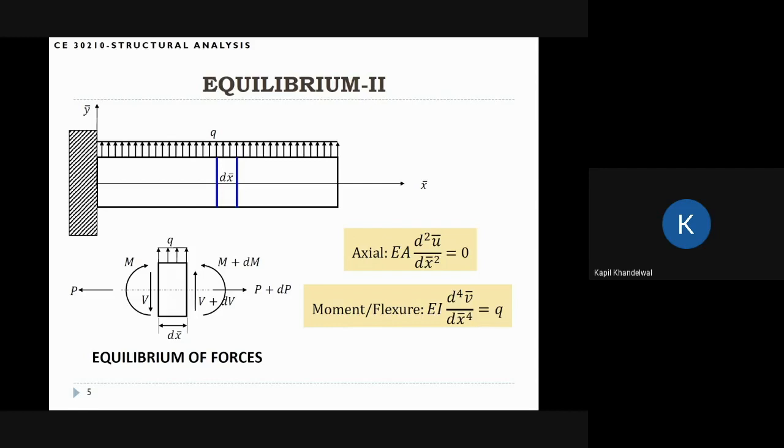Okay. And this is the case for a linear beam theory. If the beam theory was nonlinear, then we would see that these fields are coupled, and then the theory is much more complicated. But in our class, we are just interested in the linear beam theory. And in the linear beam theory, the axial effects and the flexural effects are uncoupled. So we can study these effects independently, and they don't influence each other.